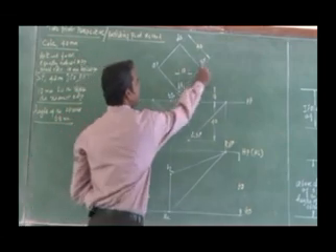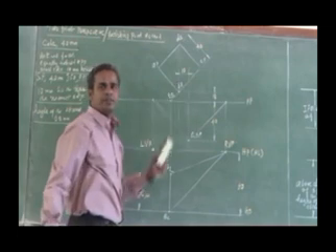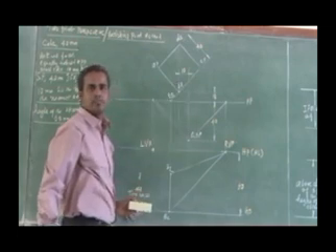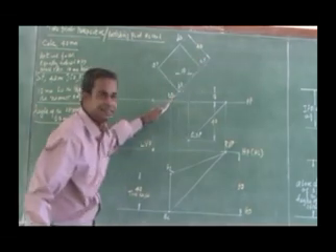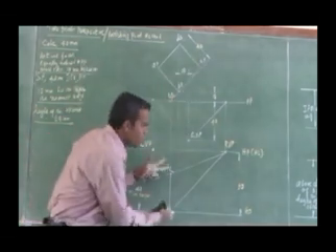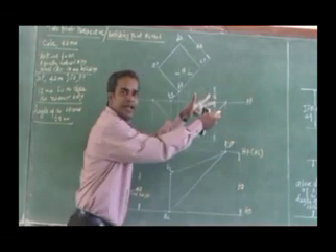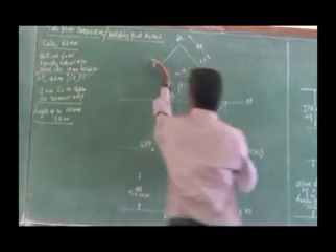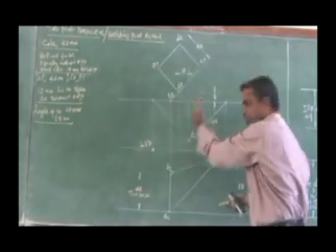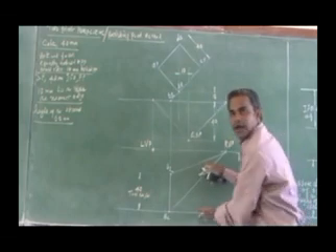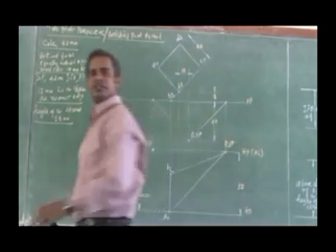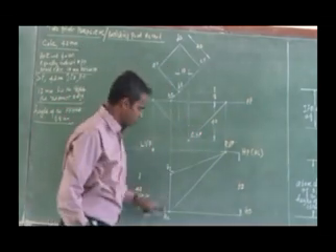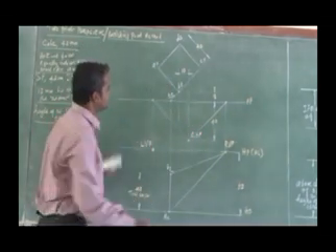So you get the intercept of BQCR. How is the intercept of BQCR obtained? You should be very clear with this. Suppose I am extending this true line like this, you have to join it to the right vanishing point. Suppose the same thing I am extending like this, I will have a true height here. Where do I have to join it? Left vanishing point. Right, that is the thing you should remember. Now I have drawn like this.